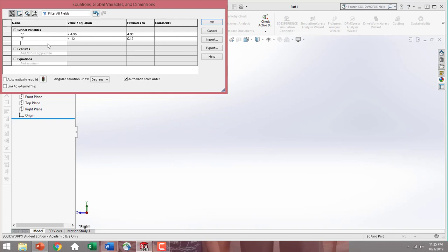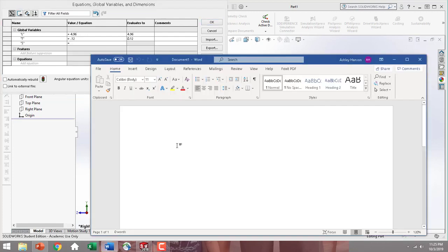And last, I'm going to add in my S value. Now this one is a variable space, so we need to solve for S. So if you're looking just at this quickly, it may look like it's hard to solve for S, but this really is a simple equation. So we take our overall length, we have our overall length equals, now we have 9 T slots, so 9T plus 8 S's. So now we just solve for S.